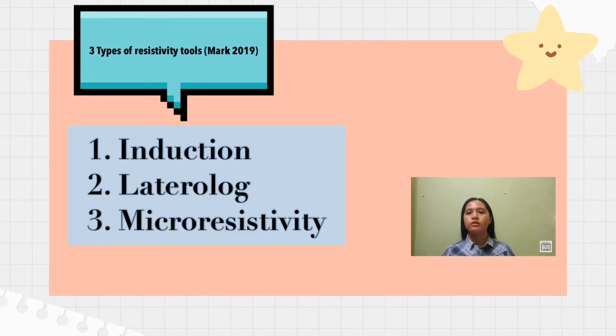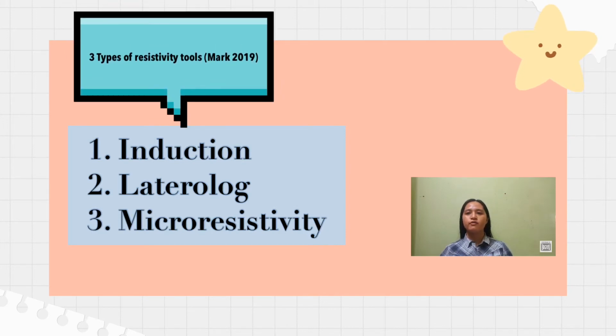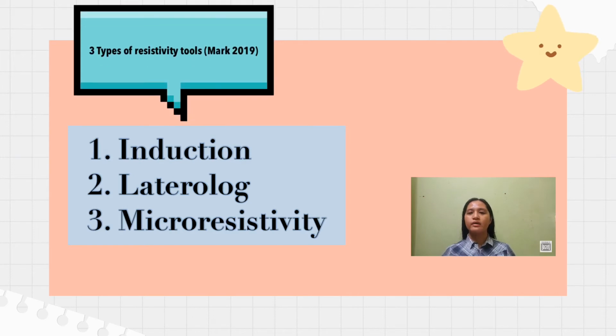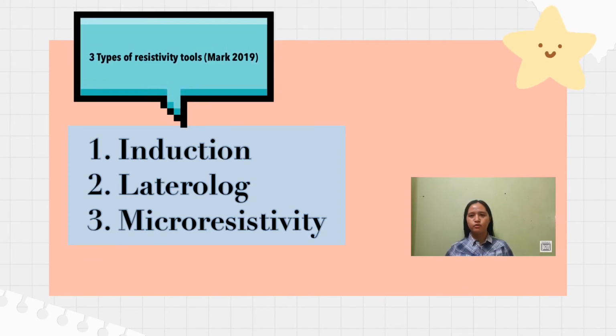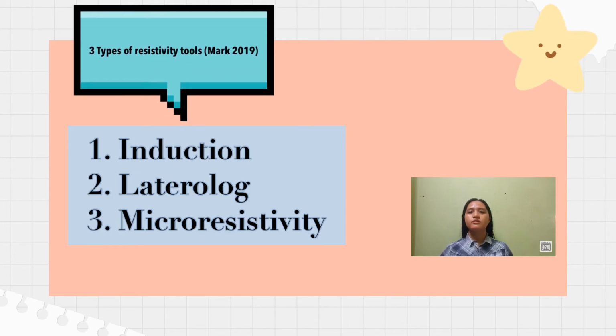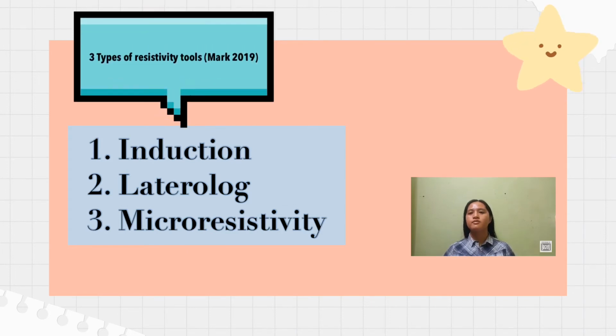So I'm going to continue on the part of resistivity tool limitations. Each type of resistivity tool has its own physical limits. Even with an ideal data set calculated in perfect borehole conditions, the uncertainty in the resistivity tool response inversion is a problem due to the limits imposed by tool physics. Resistivity tools can be divided into three characteristic types, which are induction, laterolog, and micro-resistivity tools.